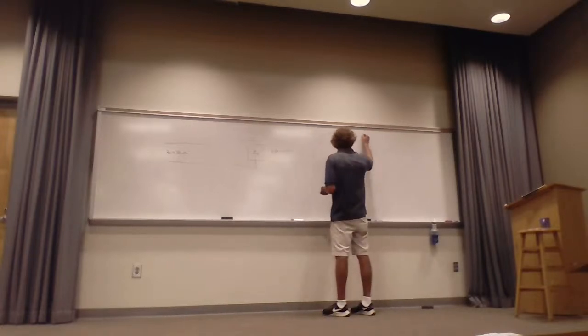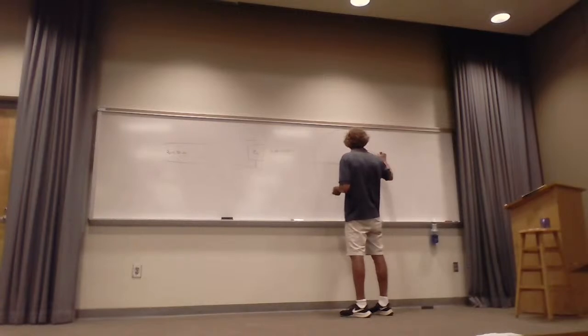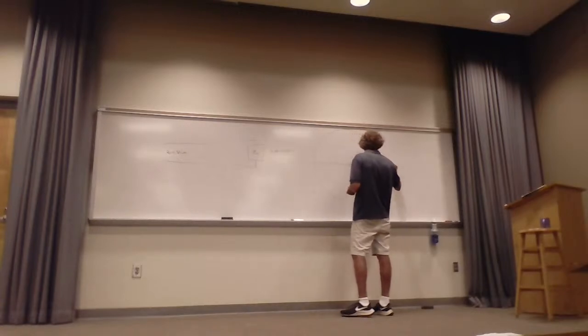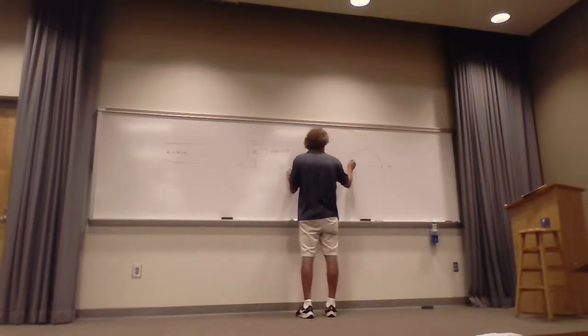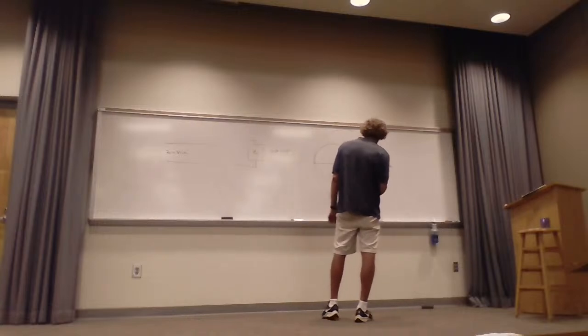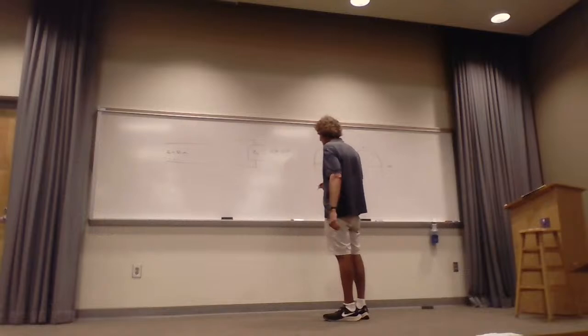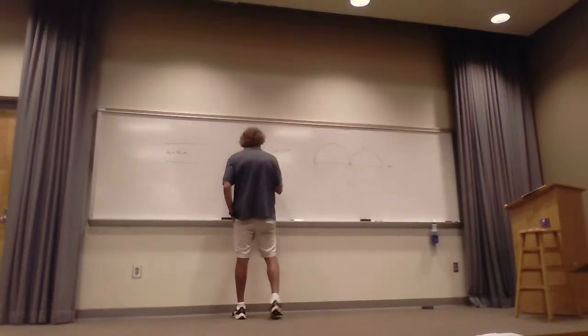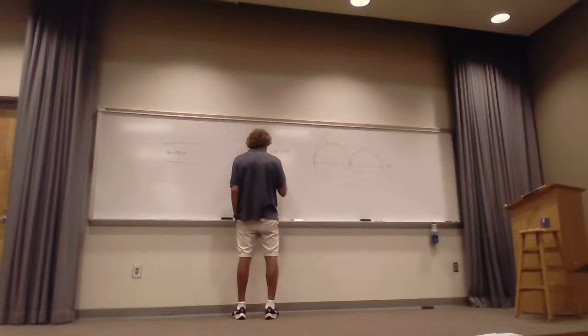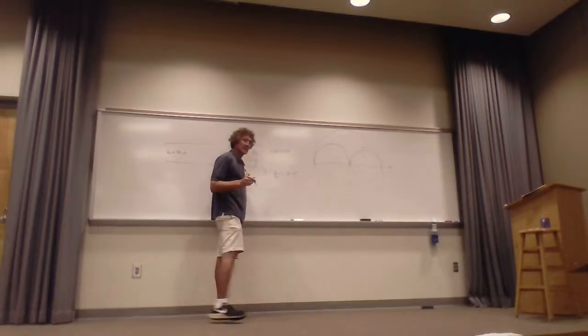So here's my big old Smith chart. Here's the one circle. Here's the rotated circle. I'm going to draw on the scale to get the idea. And now the first thing I do is plot this, where I get ZL. So ZL is equal to capital ZL over Z naught. This is the normalized impedance. And that's 5 minus J5, correct?